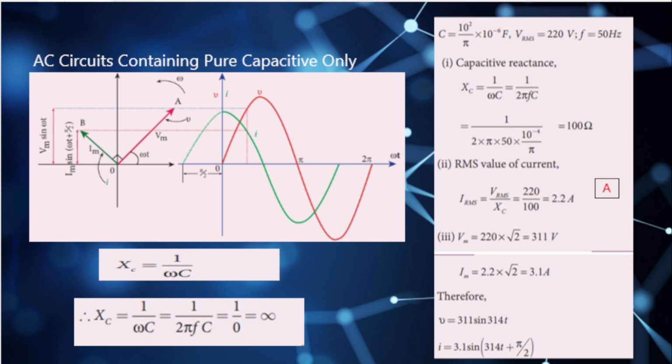Now, for a steady current where frequency equals 0, our capacitive reactance, or XC, will be infinite. Thus, a capacitive circuit offers infinite resistance to the steady current, so that the steady current cannot flow through the capacitor. And if we recall what I said back in our DC series, remember, capacitors block DC, but pass AC. Again, the polar opposite of inductors.